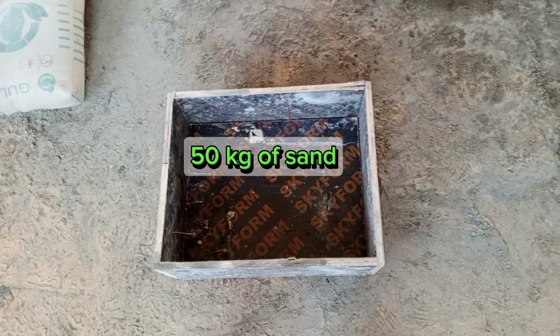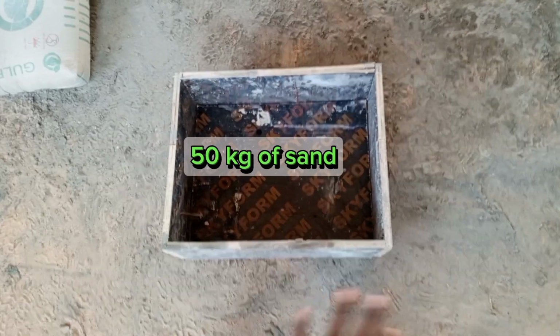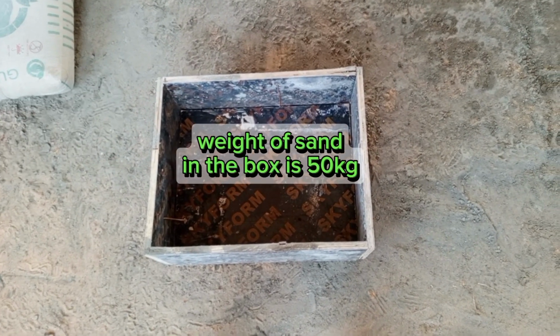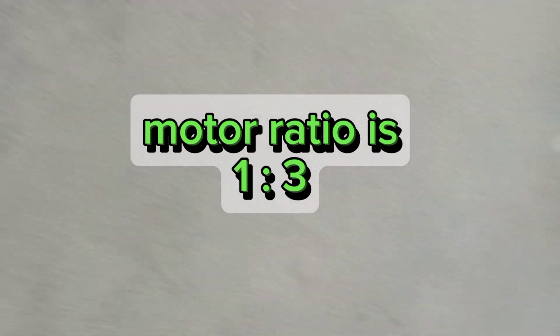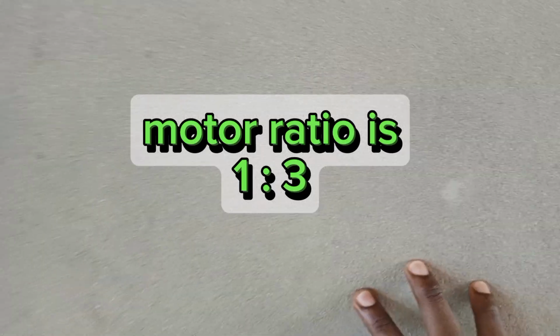We carried out the weight of this box when it is filled with sand, and the weight that we achieved is 50 kgs. Remember that our bag of cement is 50 kgs, and our ratio is 1:3. So it means that 1 bag of cement will have to be mixed with 3 equivalent weights of sand.